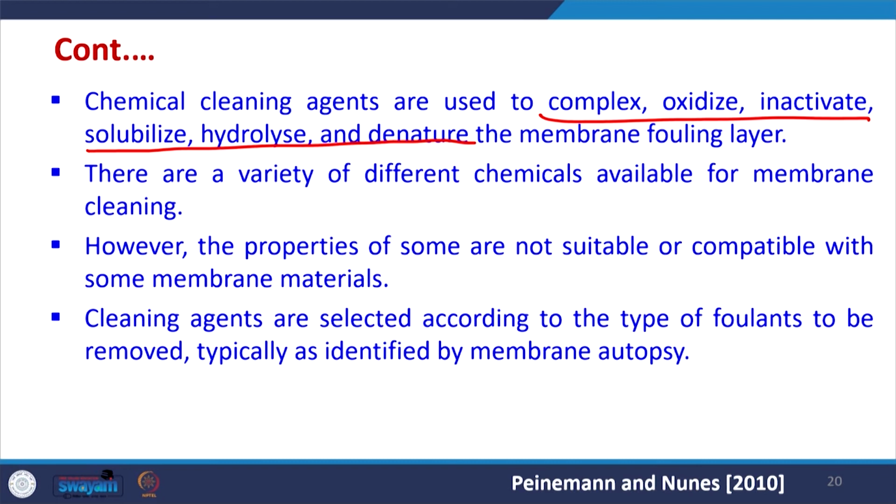Cleaning agents are selected according to the type of foulants that have to be removed, and for this the fouled membrane's autopsy or detailed characterization may have to be carried out, including physico-chemical characterization of the fouled membrane.